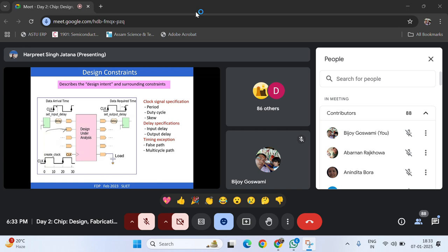So there is a constraint on how much delay they are coming with and what are the voltages, input VIL, VOH, because they are coming from somewhere else. It's not an isolated chip. It's going in a system. And similarly, output is being fed to some other chip. So there will be constraints on the input side as well as the output side.